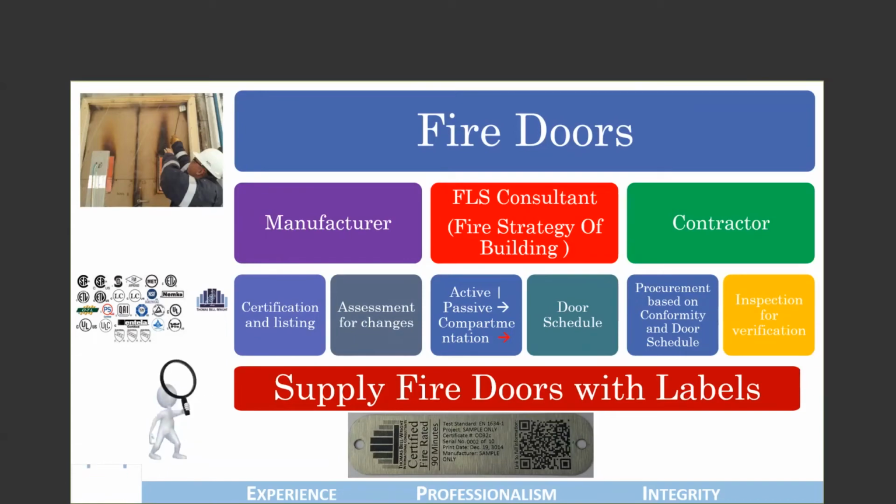Inspections are done on the basis of not only the labels but a lot of additional information provided by the door supplier on how the door set should be assembled, should be installed, etc. Because these are as critical as everything else. A fire door tested and certified to behave in a certain way, if installed incorrectly, skewed, for example, is no longer a fire door.